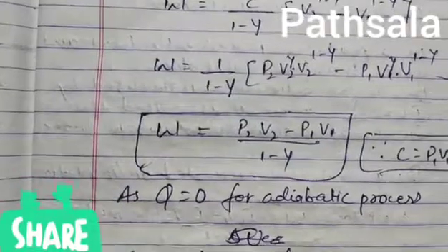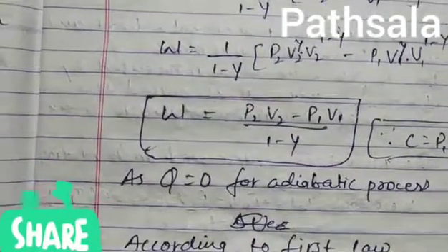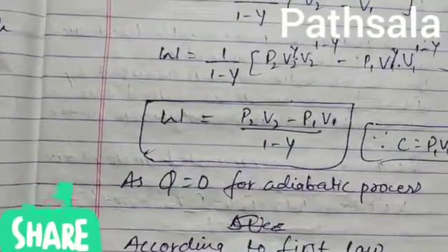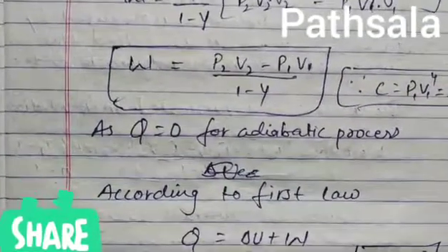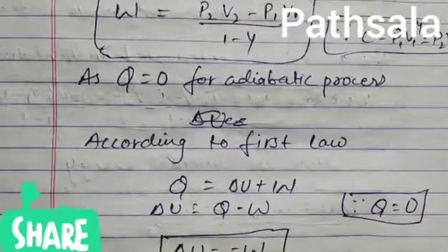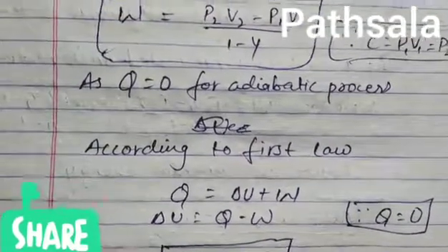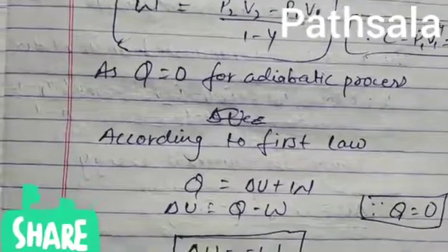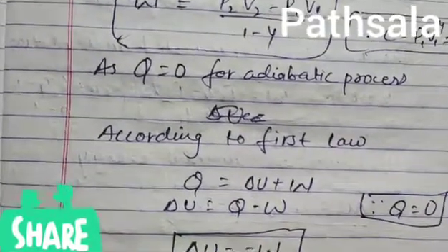That is, we get the final work done, W is equal to P2 V2 minus P1 V1 upon 1 minus gamma. That is, we get C is equal to P1. We put this value of C: P1 V1 to the power gamma is equal to P2 V2 to the power gamma, as Q is equal to 0 for the adiabatic process.